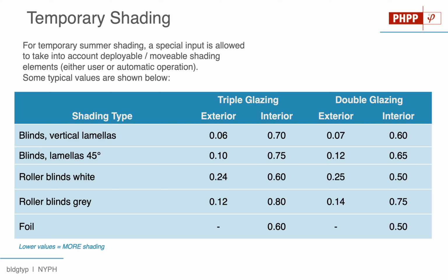Whereas the interior shades, it's not that they don't help at all. They do help. They do some, but not nearly as much shading as exterior shades. We know that the interior shades are useful. So they're most useful psychologically, giving people a sort of lever to pull when they're overheated and they need some cooling. But they're not nearly as effective as exterior shades or exterior blinds, shutters, what have you, when it comes to actually blocking out the sun itself.